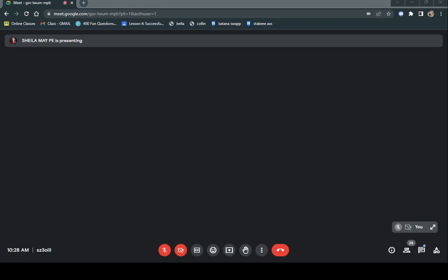Okay, next. So the reason for the label of metal oxide semiconductor FET is now fairly obvious. Metal for the drain, source, and gate connection, oxide for the silicon dioxide, or the insulating layer, and the semiconductor for the basic structure on which the N and P-type regions are diffused. The insulating layer between the gate and the channel has resulted in another name for the device, the insulated gate FET.